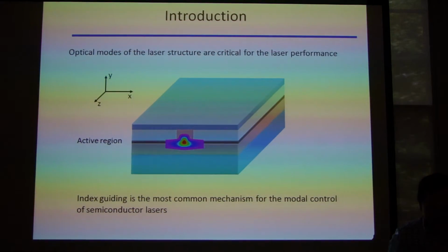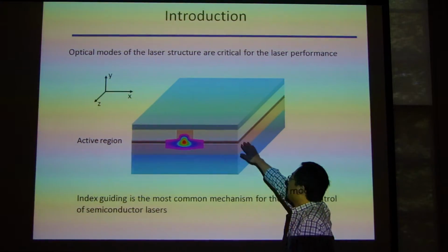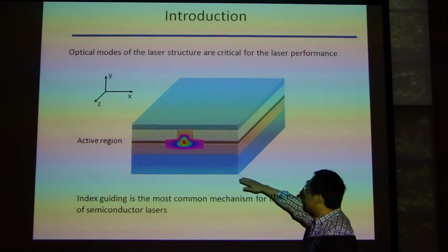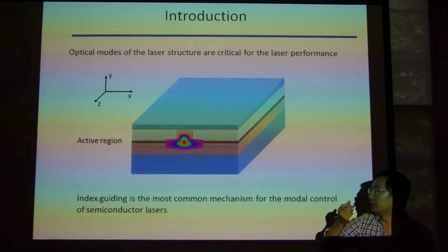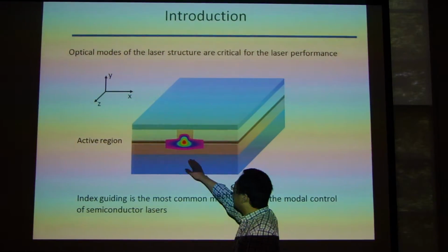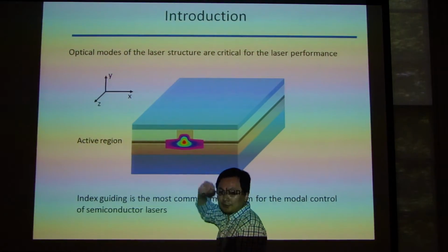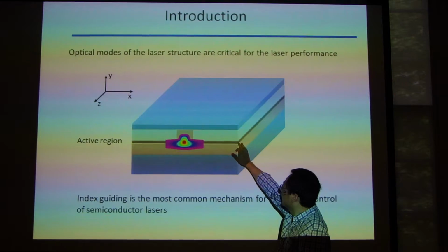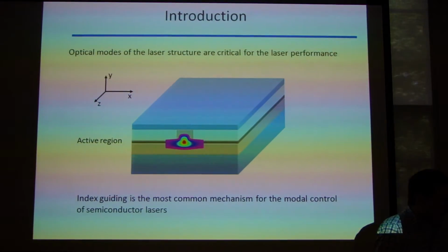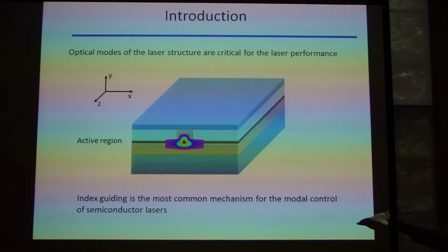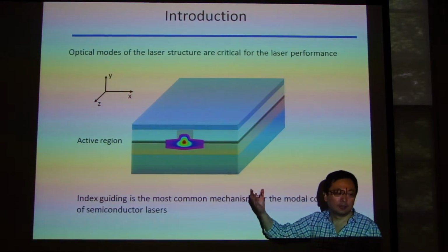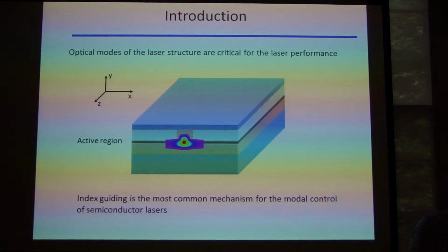So let's talk a little bit about the semiconductor laser. It looks something like this. It's a piece of III-V material. You have different layers, usually of different kinds of material. Then you guide light in a small region, usually by creating an index difference. And this so-called active region is not something particularly special. It's just that all those layers have different band gaps. In the so-called active region, the refractive index is highest and the band gap is lowest. So that way you can trap electrons and holes inside that region.